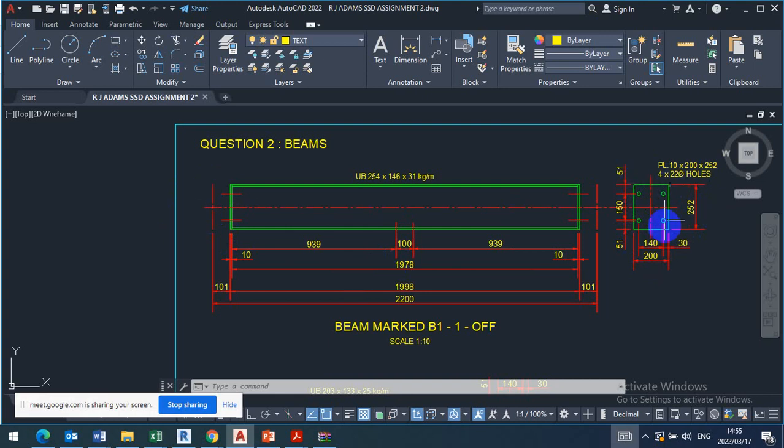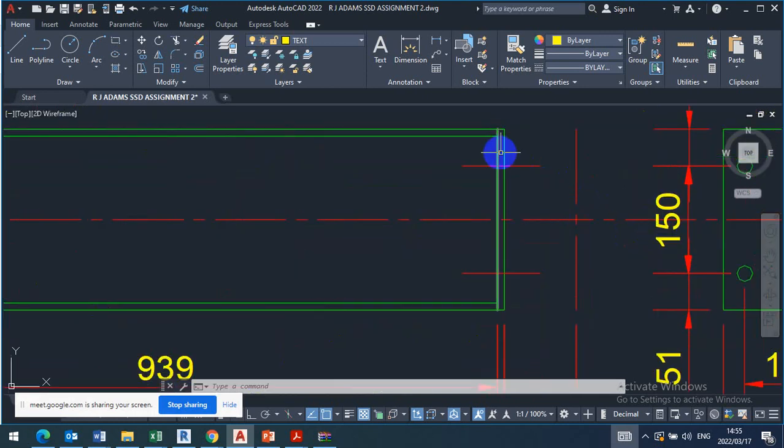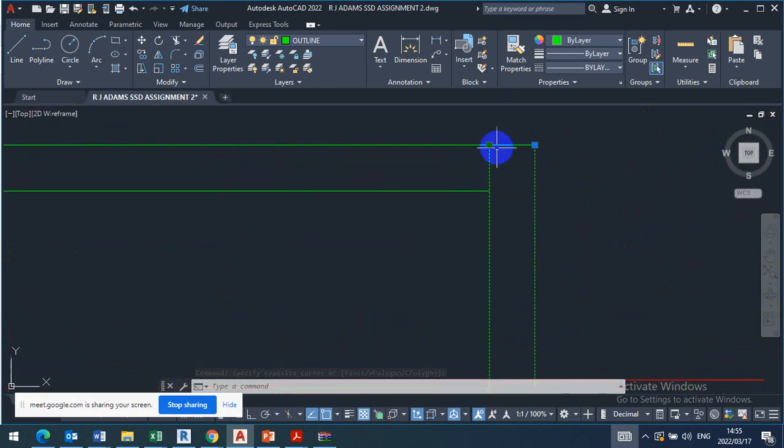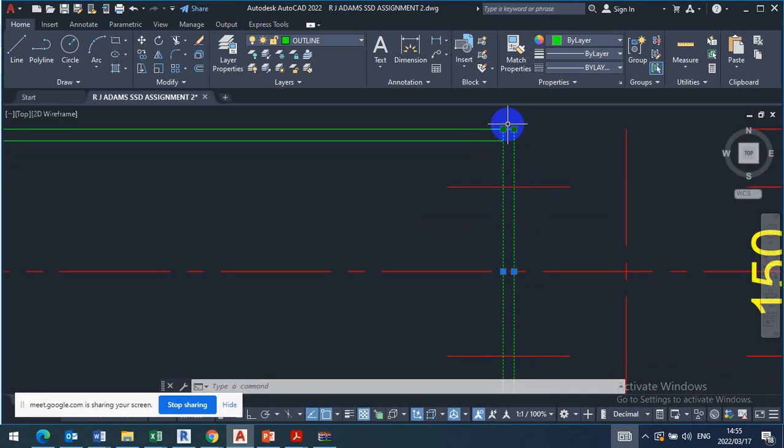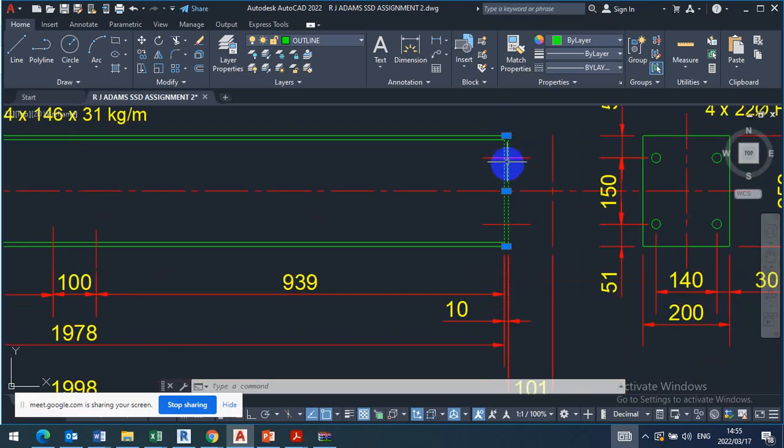This is your end plate here. Once you do the end plate, the size of the end plate should be in the height. Let me highlight it. This is the end plate. You must go up by 10. It shouldn't just flash here. You can go out by 10 to leave for welding, usually 10 fillet weld. So we usually go out by 10. Some of them prefer having it smaller as long as the I-beam is big. You can even have a small end plate here, just that size. But the hole positions are very important.